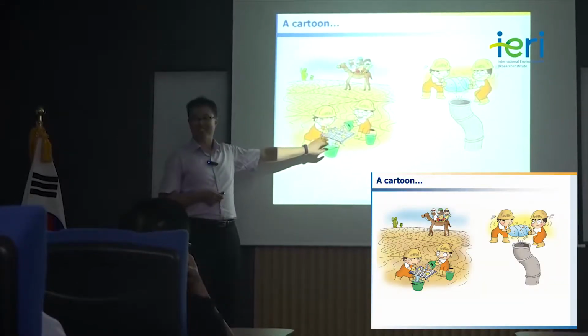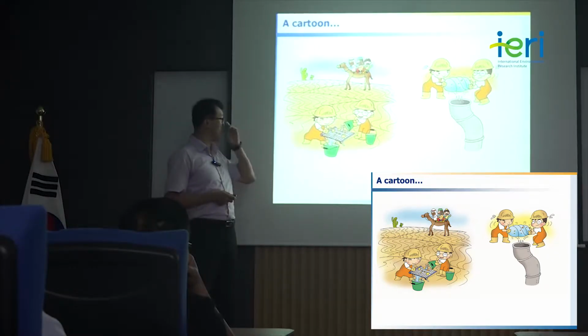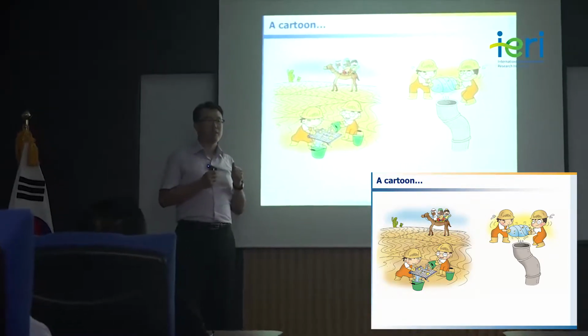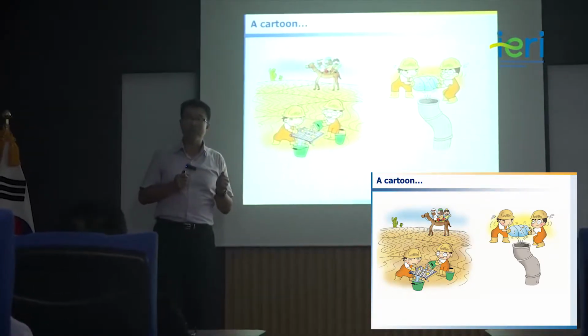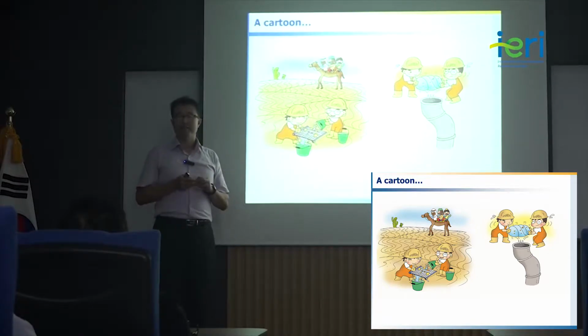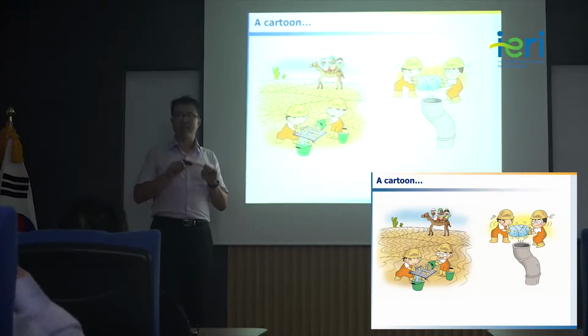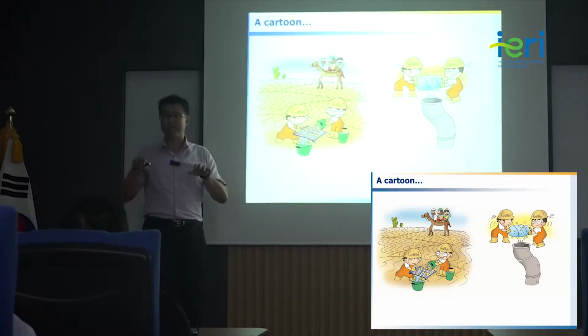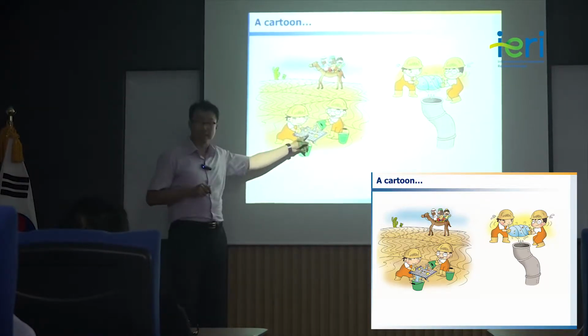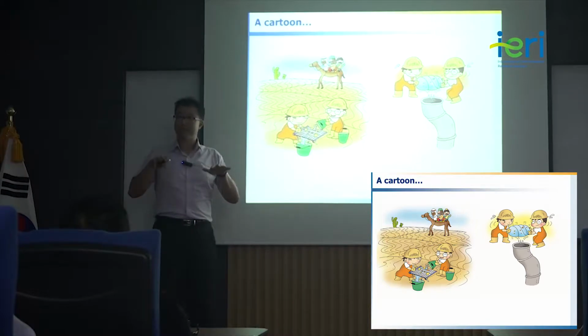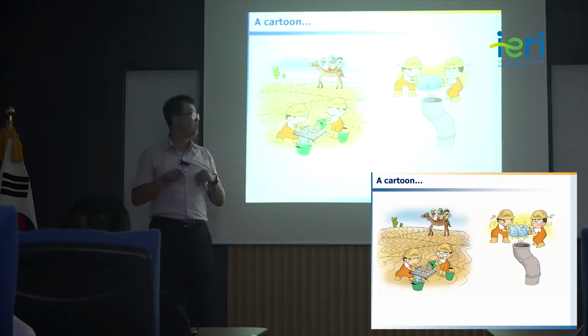Yes, filtration, that's great. We call this pre-treatment. Even if we select good seawater for desalination, the water still has some dirt, particles, and some pollutants. So we need to remove that bigger pollutant by using some filtration, or sometimes we use another membrane.